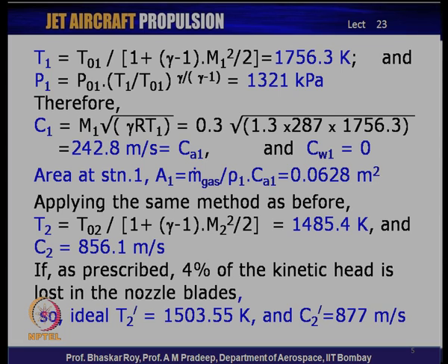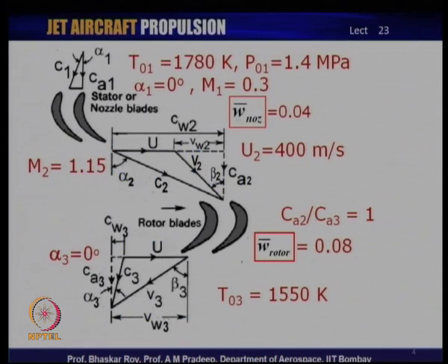So, if you keep your eye on the velocity triangle, you would see that we are trying to solve all the parameters that are shown in the velocity triangle as far as possible. And the trick of solving such problems is that if you can find all the parameters shown in this velocity triangle, you would be able to calculate the performance of the turbine completely and fully. So, one of the things that you may like to do while solving a problem is to compute all the parameters that are shown in this velocity triangle.